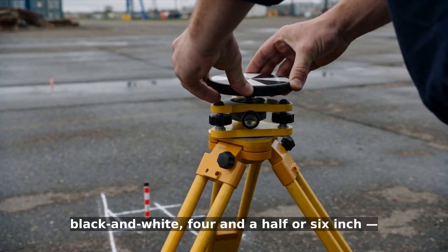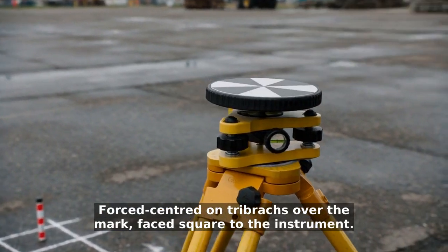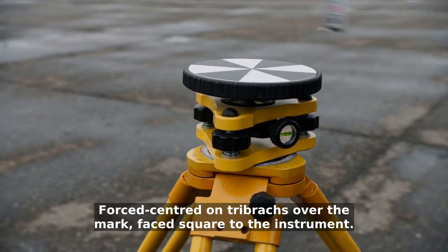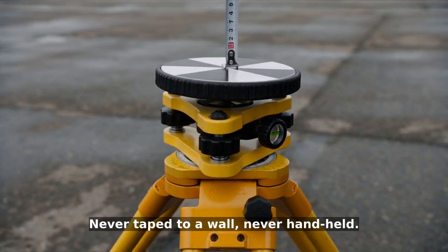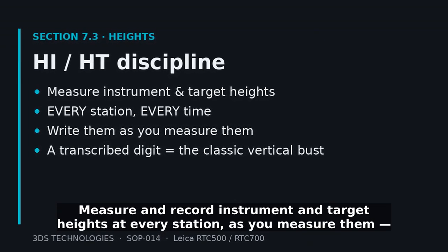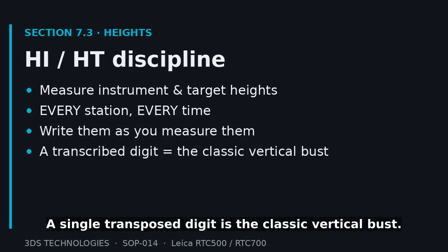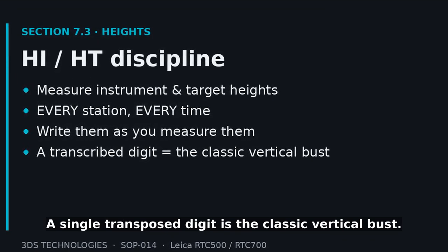Targets. Black and white, 4.5 or 6 inch, 6 on longer legs. Force centered on tribrach over the mark, face square to the instrument. Never taped to a wall, never handheld. Measure and record instrument and target heights at every station as you measure them, not from memory afterwards. A single transposed digit is the classic vertical bust.